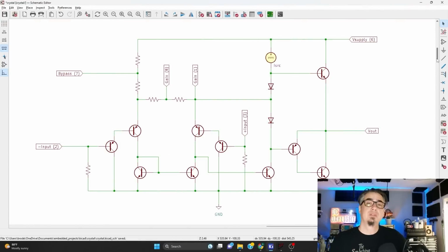So the next application we're going to look at is bypass capacitors. And just like the name sounds, we're going to use those capacitors to bypass some component. And we know that as frequency goes up, as this signal travels through this capacitor, the capacitor looks like a lower and lower resistance. As the frequency goes down, it looks like a higher and higher resistance, or impedance if you want to look at it that way. And we can use that to our advantage.